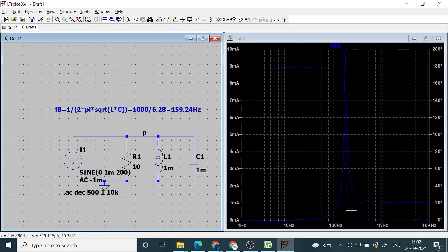Here it is 0 degree and the phase is going to 180 degree. 0 then 180, but at the center frequency it is plus 90 degree. When you plotted the inductor, what did we see? It started with 0 and then it went to minus 180 degree, and at the center frequency it was minus 90 degree.